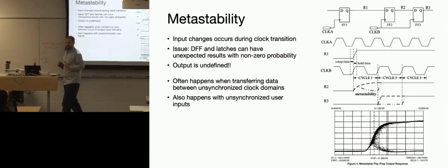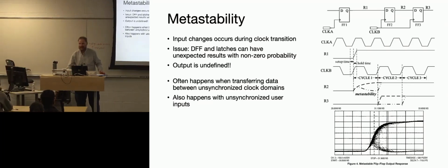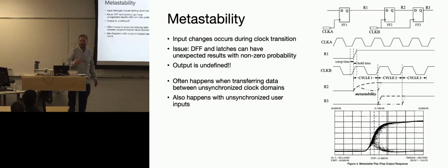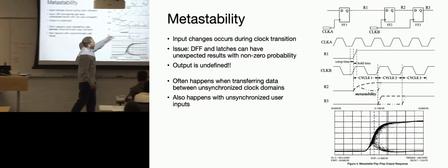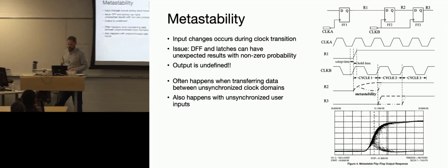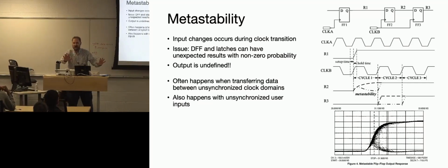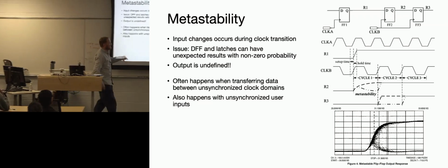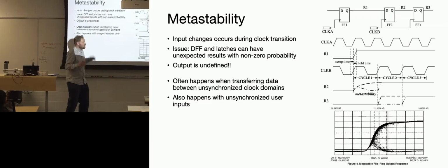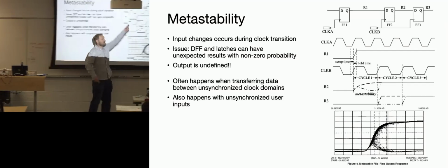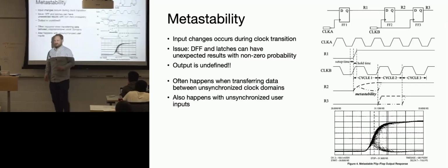But that's not good enough for medical systems. Medical people say we need to have three D flip-flops. And then the statistics say that's about the life of the universe. That is how unlikely it is that a metastability event will occur through two D flip-flops. One D flip-flop you can demonstrate in the lab pretty easily. I said a lot of stuff, so don't learn anything. The only thing you're supposed to learn from this is that if you have two asynchronous systems, you should worry that you're clocking data in the middle of the transition, and the way to get around that is two D flip-flops.